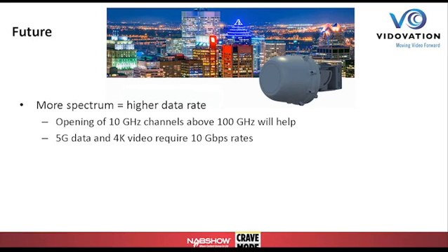Whether it's more IP-based versus baseband video, our gut is telling us it's going to be more IP-based. You could run very low latency encoders, very high bit rate for 4K, still maintain good fidelity, and just have the flexibility of a more diverse IP link as opposed to a dedicated SDI link or 4K SDI link.